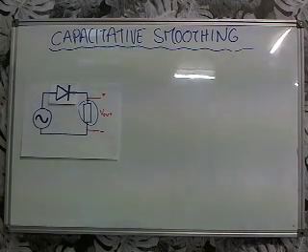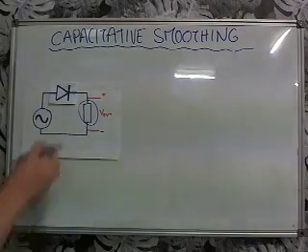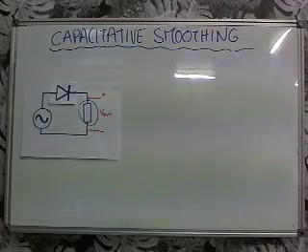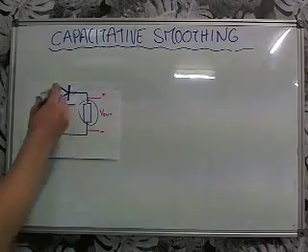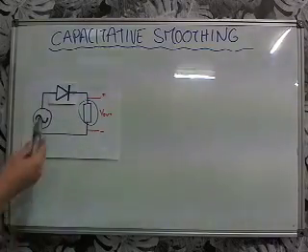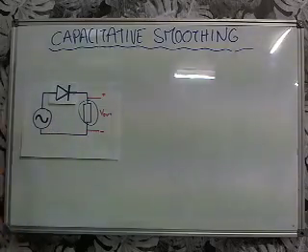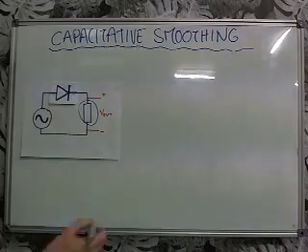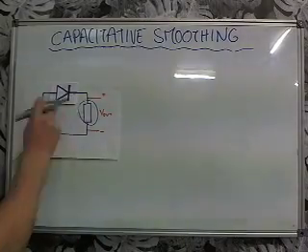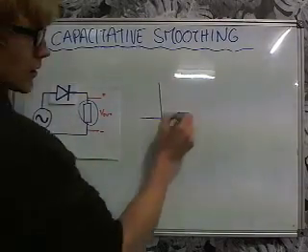Okay, so in the last video, we learned about capacitors and time constants. In this video, we want to talk about how we can incorporate that capacitor into a rectifier circuit like this one here, this half-wave rectifier, and see how that helps us to achieve that constant DC output. So again, let's just look at the output of this half-wave rectifier.